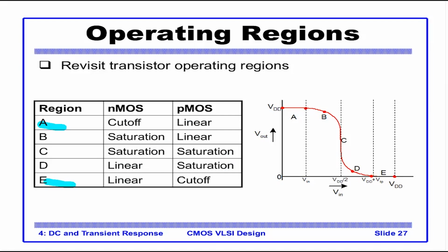Why does this happen? Now the drain voltage is constant here. What is changing is the gate voltage, the input voltage. So when the input voltage or the gate voltage is low, the drain voltage being higher pushes the transistor into saturation, and when the gate input keeps increasing, VDS decreases, since the transistor comes out of the pinch off region and goes into linear.